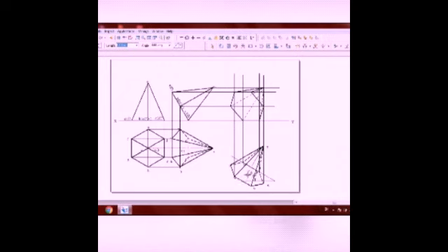There is the axis line from the base projected to the top, that is the front view. Join the axis line and convert it into an axis line, with the symbol of short dash and long dash. There is the end of it. The trimming is remaining. As I have already told you, you can zoom in and look for errors. Yes, that last line from the apex appears to be not touching perfectly. That can be seen by further zooming.